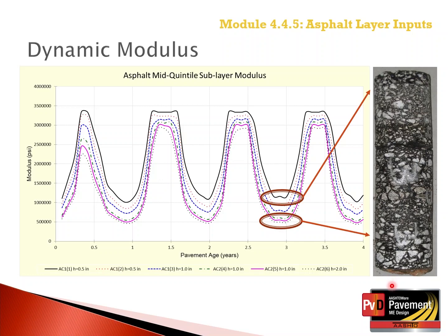Remember, the PMAT software assumes the daily truck traffic for flexible pavements is equally distributed between the hours of a day. As a reminder, the truck traffic hourly distribution factors are not used for flexible pavements. The hourly distribution factors are only applicable to rigid pavement design.